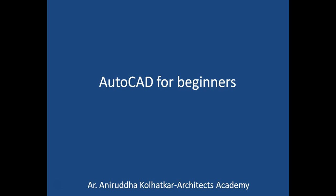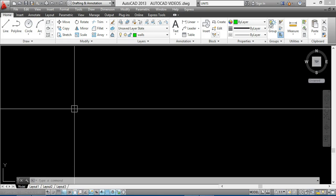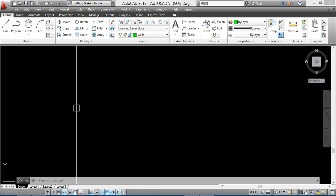AutoCAD for beginners. In today's lecture we are going to learn about setting units for a drawing in AutoCAD. Now you know that architects work in different types of units, and there are basically two types of units which we work in. One is called the feet and inch system and the other is the metric system. Now we have to set up in which system we are going to work before we start a drawing.